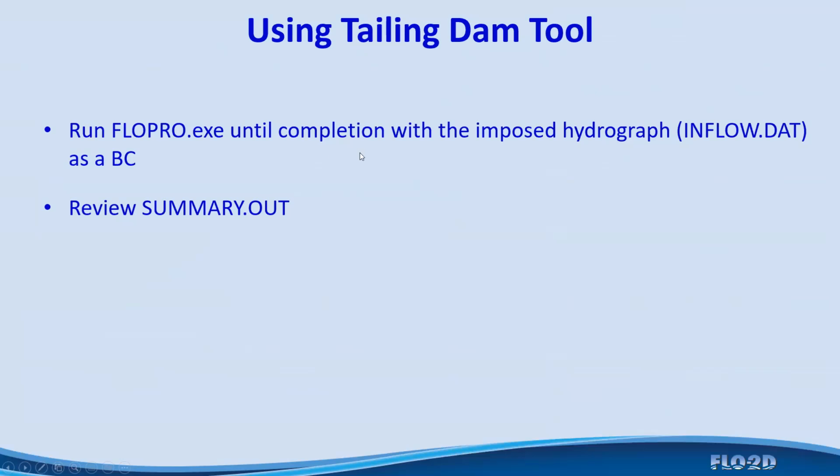You know that for this particular case, my mudflow hydrograph is entering this volume in 1 hour, because I selected 1 hour as the entire event time, but you can run FLO-2D for 3 or 4 or 5 hours and see how this mudflow is moving downstream in your system. And then after you finish that, I always recommend you review the summary.out, okay? So again, FLO-2D is going to route this mudflow downstream, and you are going to be able to see the mudflow progression in your system.